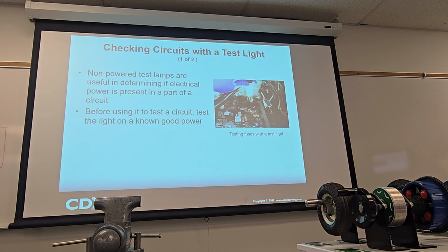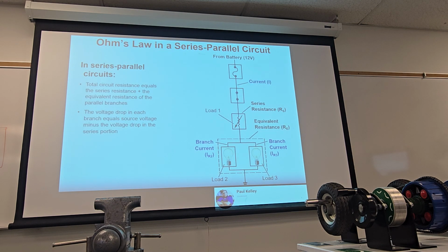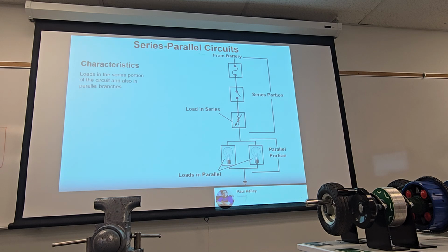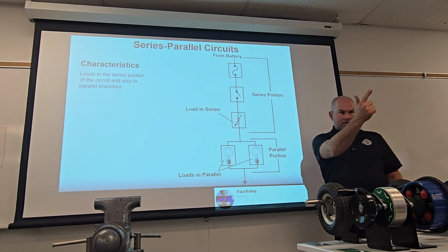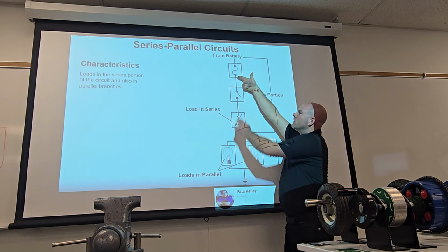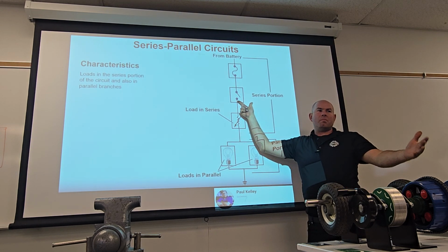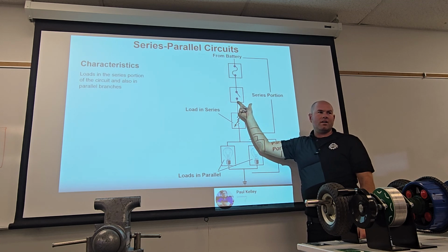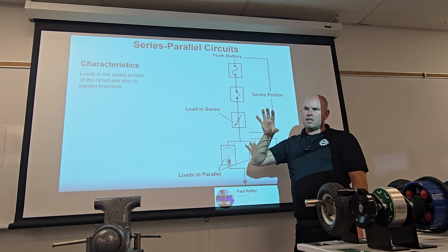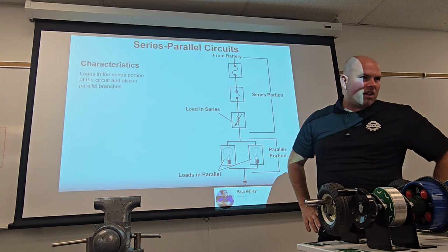I'll tell you what, I'll even back up to really nail this down. Let's just say we went to this. If I had a test light, okay, you ready? Test light glows. Test light glows. If this switch is closed, what should happen here? Test light should glow, but if the test light doesn't glow, what's wrong? See, so a test light is a usable tool, and you can buy them for $12.